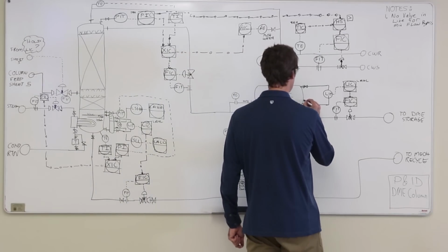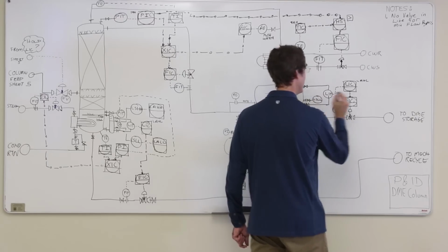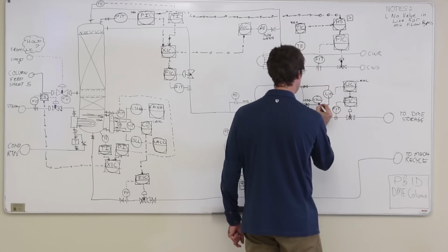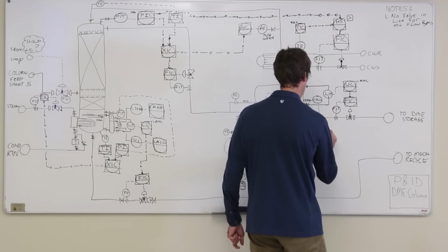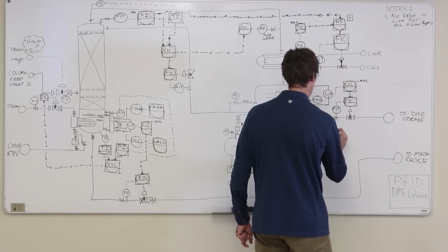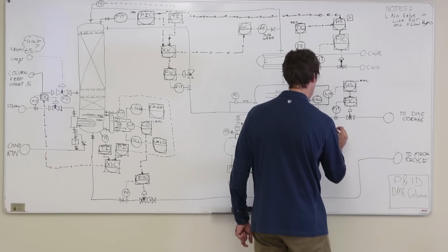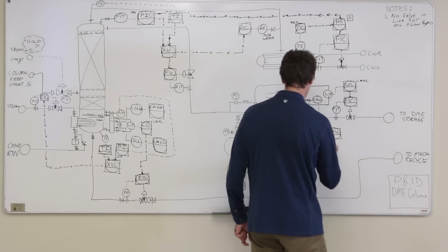So what we're going to do is show a level switch low. Do a low low because we have a low already on the transmitter. Like that. We'll put an alarm in at the same time in the control system so that we know about it. Like that.